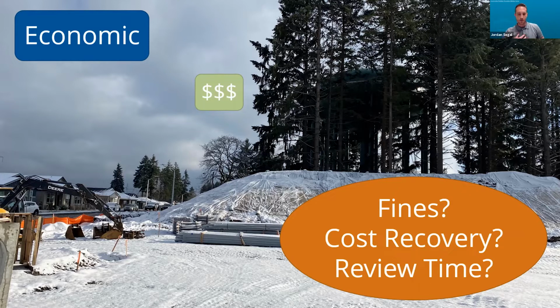I am sometimes a reviewer of development permit plans with the city of Kirkland, particularly with stormwater, either permanent design or these temporary erosion sediment control plans. If there's something that I don't find to be protecting the surrounding properties or a natural water body, I might have to make a comment on it, which could extend the review time to another submittal.